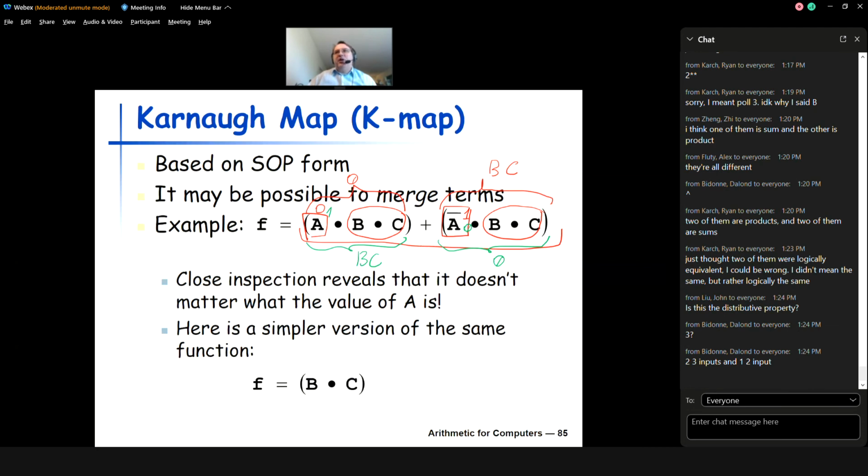Okay, exactly. So you can start with the second layer or the first layer, however you feel more comfortable thinking about it, right? We have one operation in the second layer, this OR gate, and we only need one because we have one OR. It has 2 inputs, so that means that in the first layer there are 2 gates, right? And each of them is a 3-input gate.